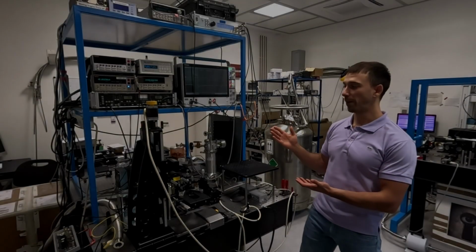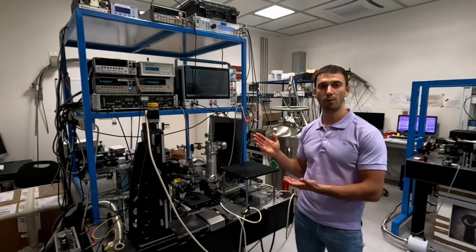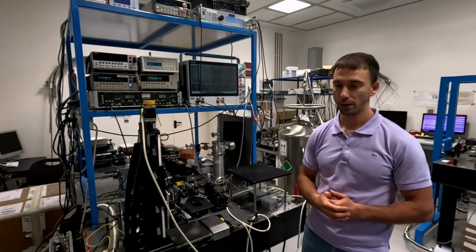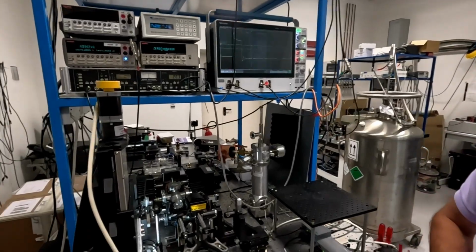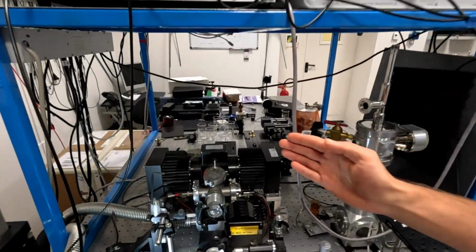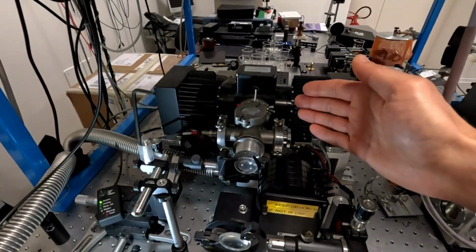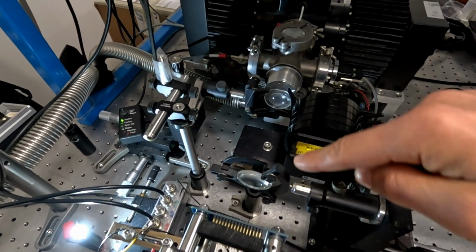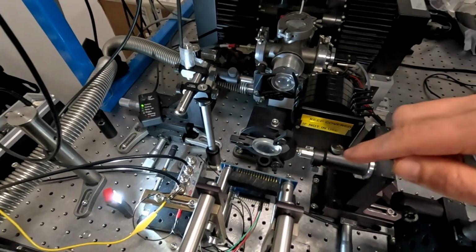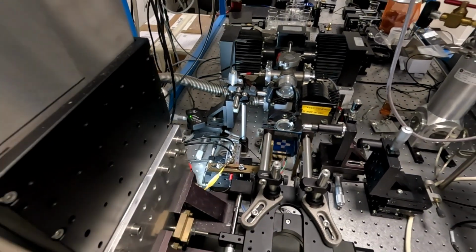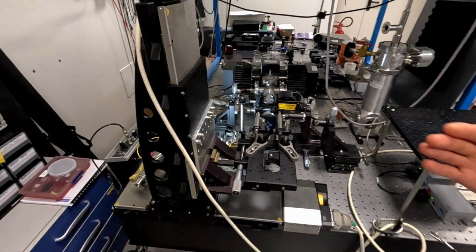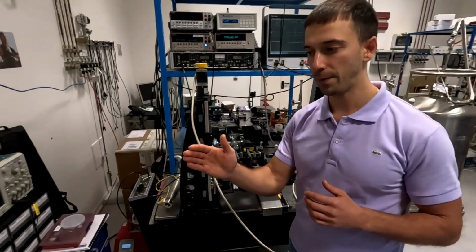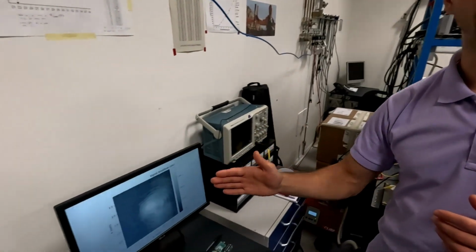This is the experimental setup that we use to perform both electrical and optical characterization of our photodetectors. It is based on a terahertz quantum cascade laser enclosed in this Stirling cryostat. The light of the laser is focused on the detector. The precise motion of the detector position allows us to maximize the signal and reconstruct the beam shape in the focal plane.